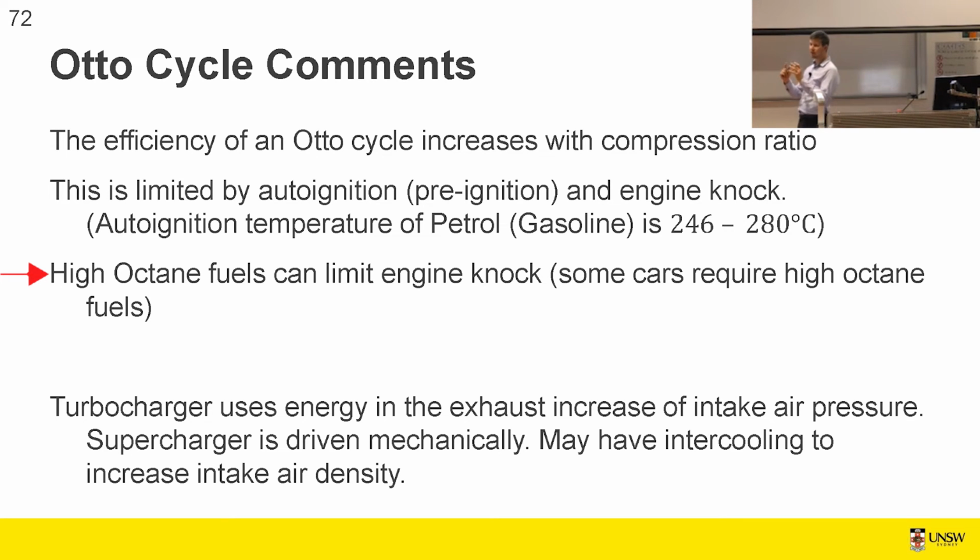Does anyone own a car that requires a high-octane fuel, where the manufacturer recommends, yep, there we go, to use whatever it is, 98, yeah. Cool, so that's trying to prevent engine knock by increasing the auto-ignition temperature and in some ways slowing down the process of ignition.